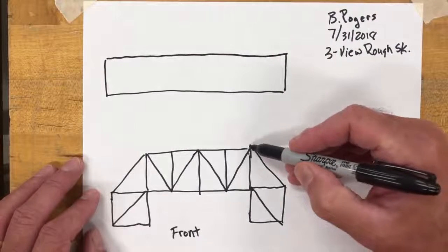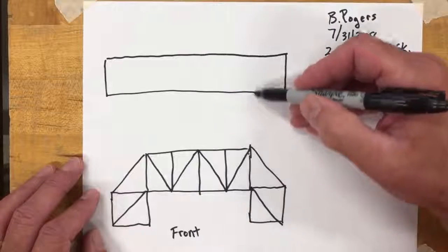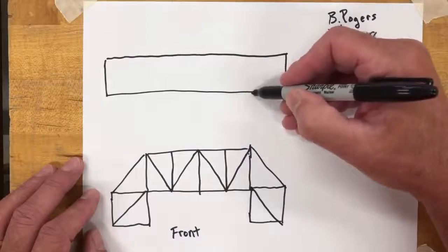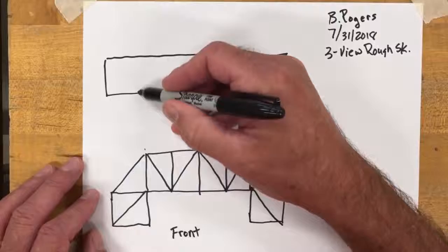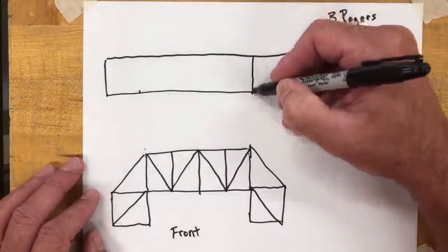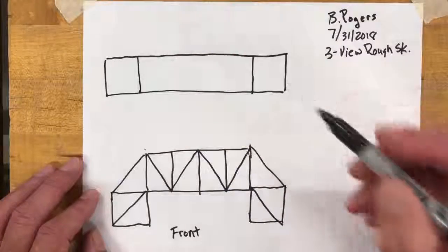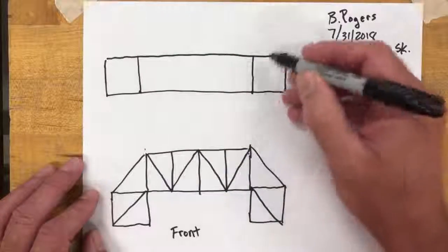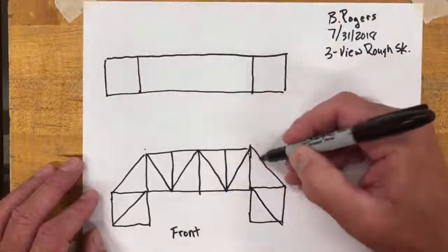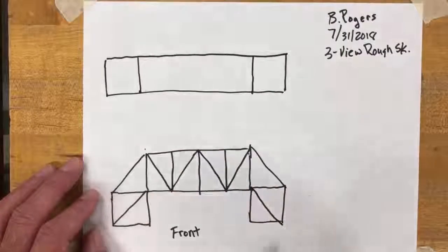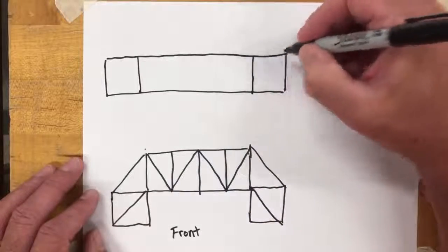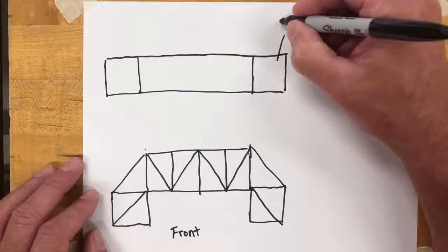Now, I use my front view here to start projecting up where the top of the bridge is going to be located. So you see right in line with that, I put a couple of dots. And then I'm going to draw the top of the bridge right here. This rectangle right here is the top of the bridge. These openings right here are the slanted parts. And we're going to put a label here.